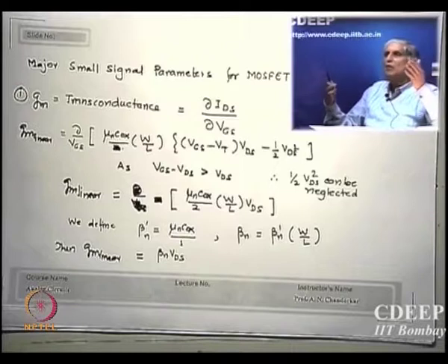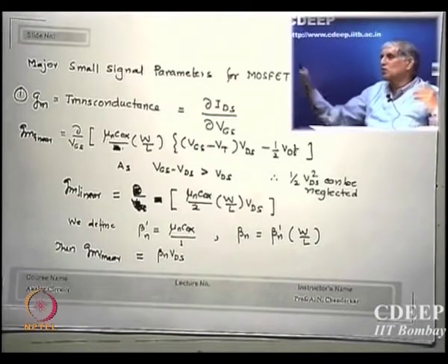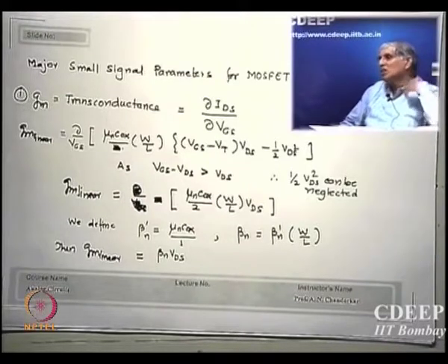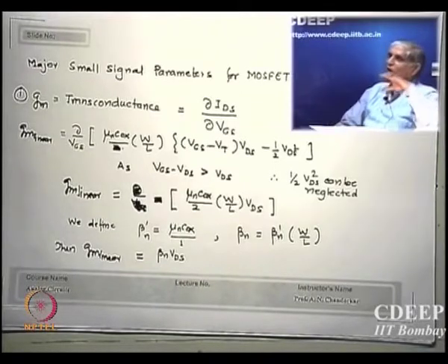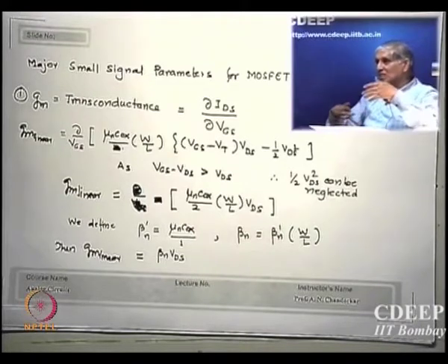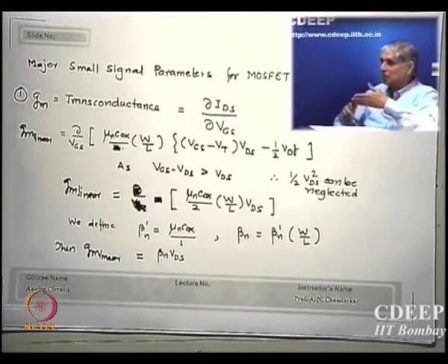All that will happen is it will have a matrix, because I will be I1, I2, I3, V will be V1, V2, V3, and therefore G will also have a similar matrix value. So you will have some kind of a matrix solver. So all that SPICE does is this, but SPICE requires models for the transistors. So it requires constants W by L, COX, TOX, VT, everything has to be specified.